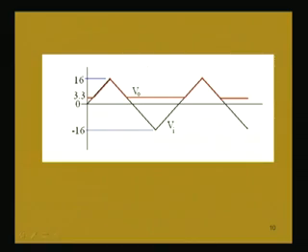So, we get the output voltage as a constant voltage for the conducting part. This will be constant when the input voltage is less than 3.3, that means this is the conducting region, and when the input voltage is greater than 3.3, the diode does not conduct.